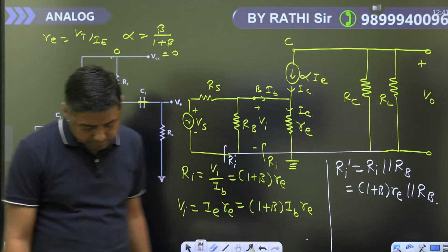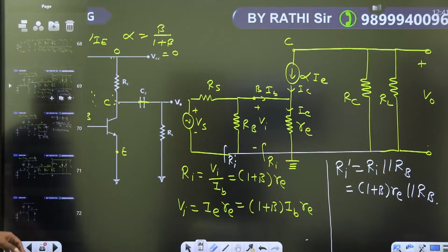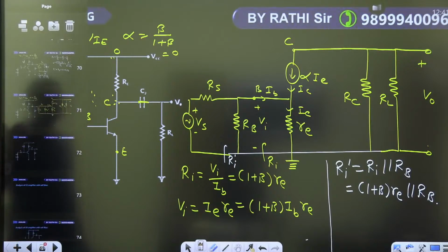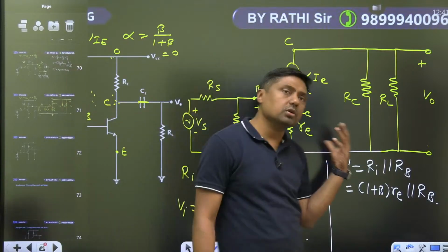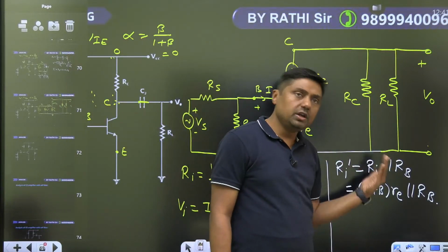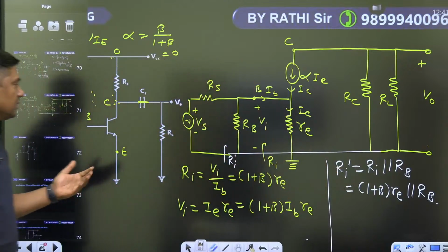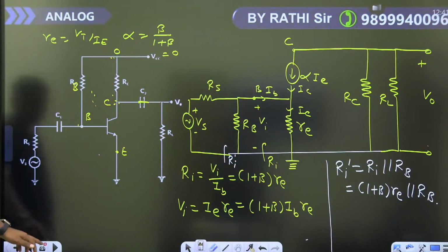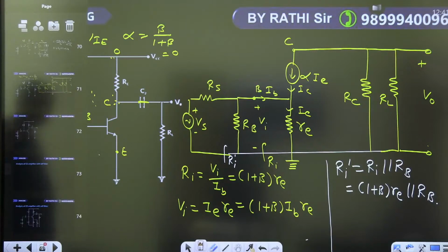Now, that is a small signal model, guys, with RS. So in this way we can solve the fixed bias circuit. 99% of questions are based on this diagram. Very easy. So use this concept, get the voltage gain, get the idea about that question. At the end I will give you the shortcut. Then this is about the fixed bias circuit.